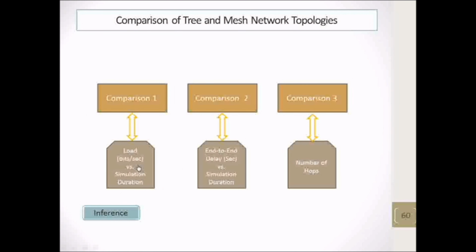In order to understand the output, we have to look through this table. If the RS232 voltage is in the range between plus 3 and plus 5 volt, the output voltage of the Zigbee should be 0, and similarly if the output voltage of the Zigbee is high, the RS232 equivalent voltage should be in the range between minus 3 volt and minus 15 volt. So the output from Zigbee here is 3.96 volt, and the output from the corresponding pin is minus 7.48 volt, which is in the range specified before.